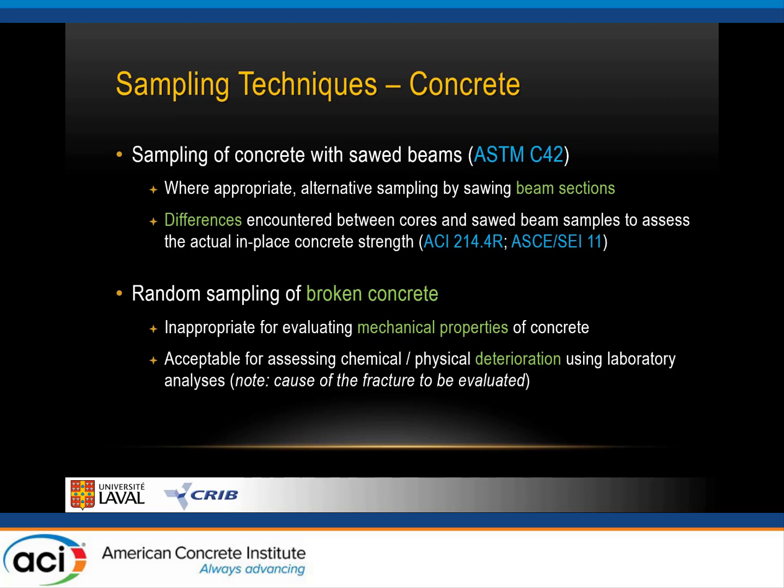Typically, broken concrete can be useful to provide further information with regards to chemical and physical deterioration of concrete, but it will generally be avoided completely when it comes to strength evaluation.